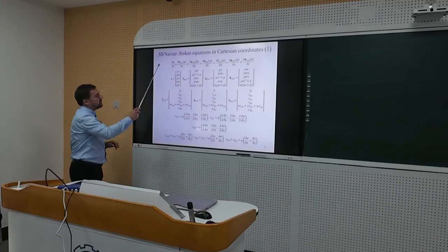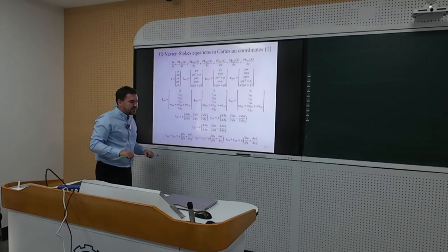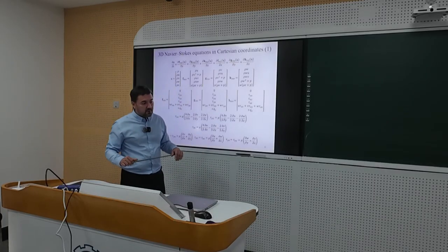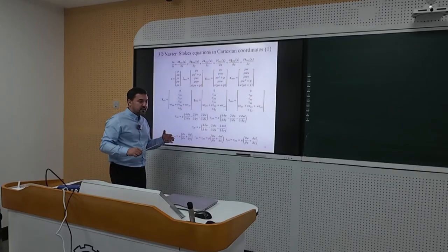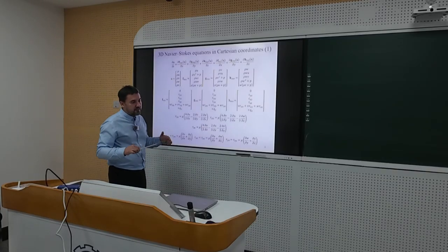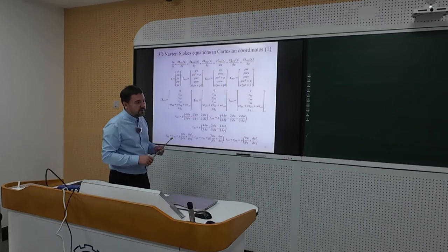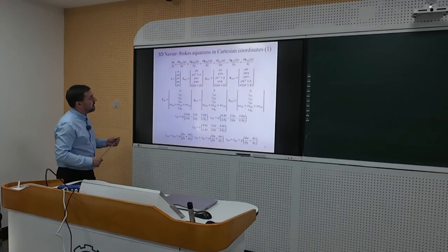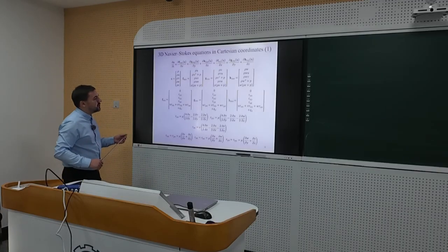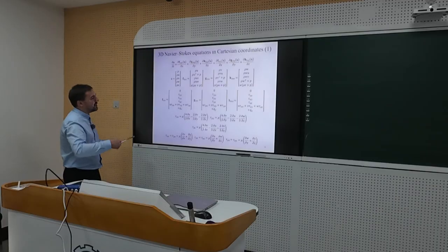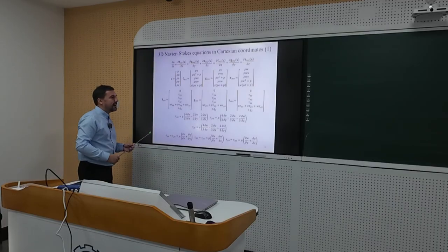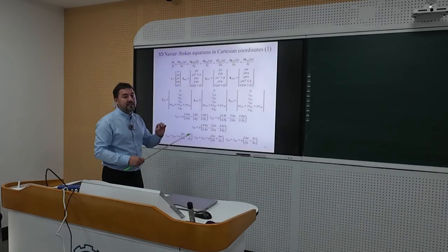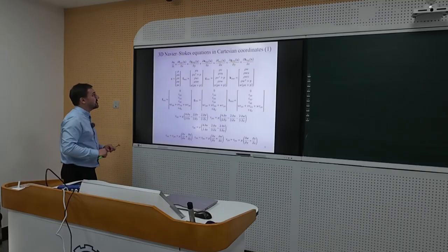When we solve Navier-Stokes equations, 1D is not very important, especially for high-speed flows, because viscosity plays a significant role in boundary layers, and so these effects are 2D or 3D. That is why, just for your general understanding, generally speaking, we should know how to solve this system of equations. You can agree that it's a bit more difficult than just one toy model, one simplified model, the so-called Burgers equation.